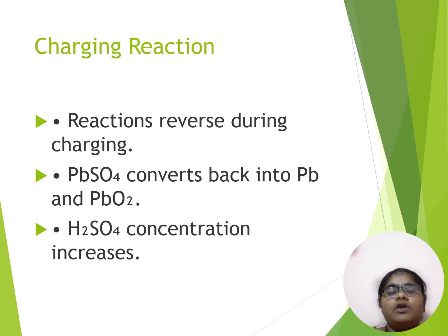Charging reaction means the reaction reverses during charging. Lead sulfate converts to lead and lead dioxide. H2SO4 concentration increases during charging, and during discharging the concentration of H2SO4 decreases.